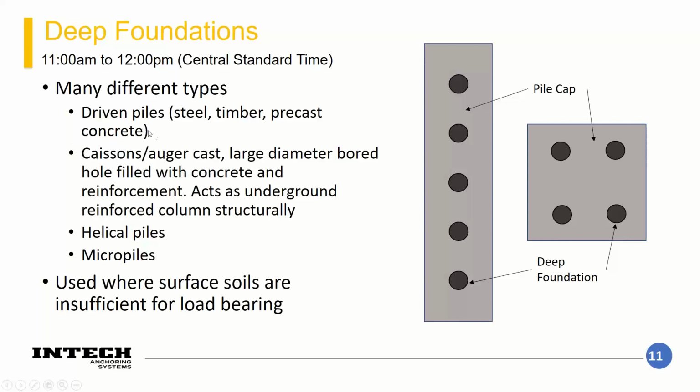Driven piles are probably something everyone's familiar with. These are very common in large, heavy structures, bridges, and big buildings with very high loads. They can be made of steel, timber, or precast concrete.